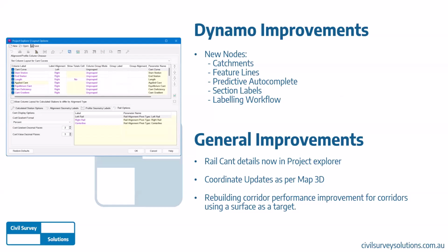There is also a new node for section view labels to automate the creation or modification of section view offset elevation or depth labels. There are also some enhancements to the labeling workflow. There's a new sample graph in there, the Civil 3D Create Lot Labels, sitting under the Civil 3D library. This shows you how you can automate the placement of spot elevations and general segment labels for your lots. All right, there've also been some updates to the core of Dynamo, so there are some improvements there.